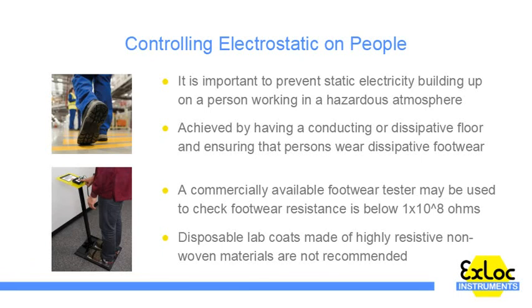As mentioned, clothing can hold static electricity, but it is not considered to be a major risk if the person is wearing suitable footwear. However, the excess of static electricity that can be generated when removing clothing means that this should not be done in a potentially explosive atmosphere. Disposable lab coats and oversuits made of highly resistive, non-woven materials are not recommended.